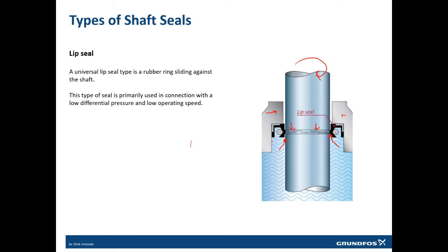So what will happen if you don't have the water? This will get damaged very soon. So having no water is a big disaster for a pump, because what you have to do is open the pump and change the shaft seal. Changing a shaft seal is again a wear part. So you need to change the shaft seal after some time of operation, because this is rubbing against it.